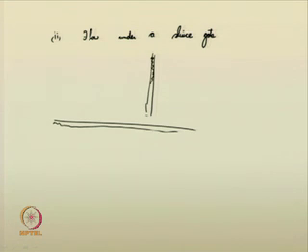Say there is a sluice gate that is blocking the flow, maybe in a uniform channel flow. You know that there will be a gradually varied flow profile in the upstream of the sluice gate, that is quite understandable. Now, due to the narrow passage at the bottom, the flow gushes up and the flow profile changes like this. So, in this small stretch itself, the curvature of the flow is changing rapidly. So, it is having a rapidly varied flow profile.